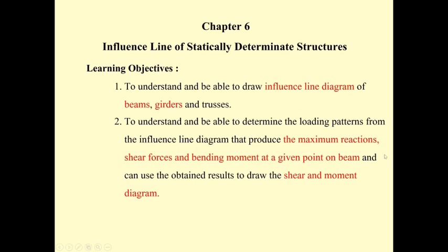So we apply learning objective 1 to find the loading pattern, from the influence line diagram, that will produce maximum reaction, maximum shear force, and maximum moment at a given point of the beam, and can use the obtained result to draw the shear diagram and moment diagram.